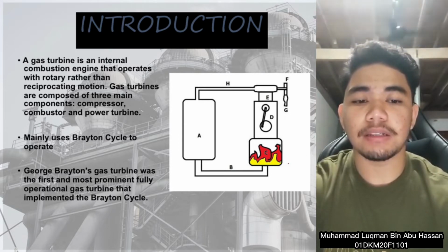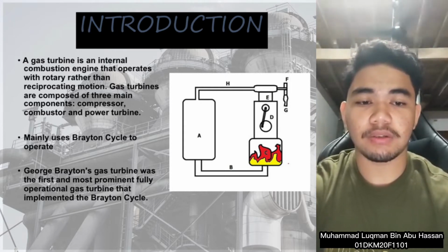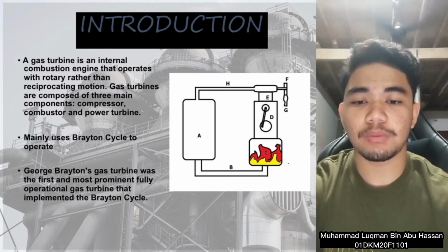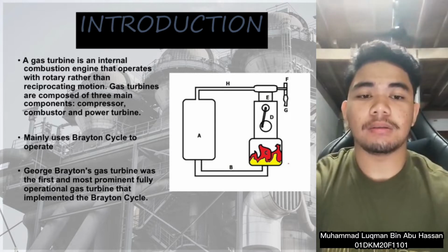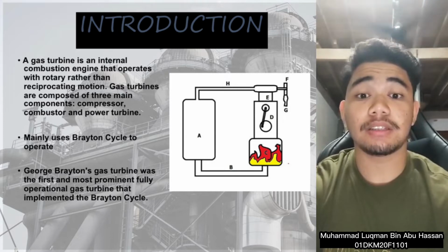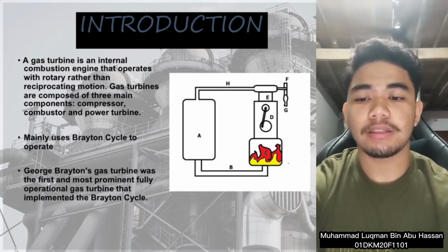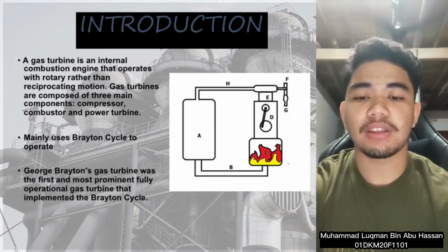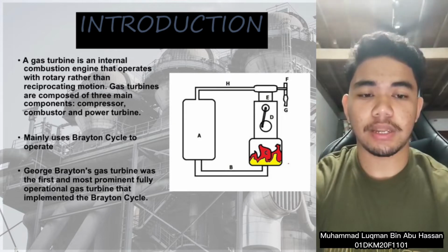The idea behind the Brayton cycle is to extract energy from flowing air and fuel to generate usable work, which can be used to power many vehicles by giving them thrust. The most basic steps in extracting energy are compression of flowing air, combustion, and then expansion of that air to create work and also power the compression at the same time.